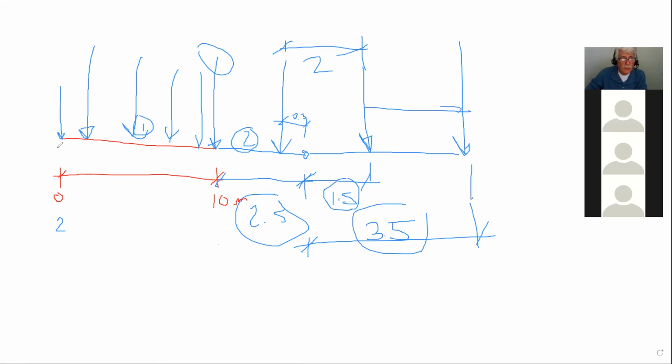When you add your members, make sure you go from here to here, because even when you apply the loads, the program is going to look at how you put your I and your J node. So on the third member, this is member number 3. The first load is at 1.5, and the second load is at 3.5. And you're done for this member. Then you got to go to the next one, right? So this member goes all the way to here, and then you have to decide where this one starts on this member.